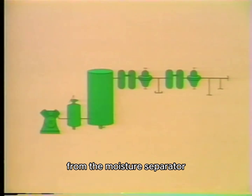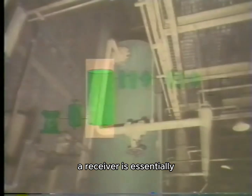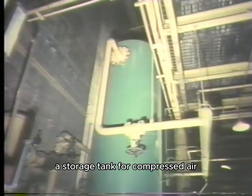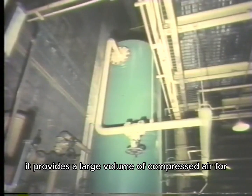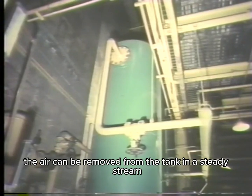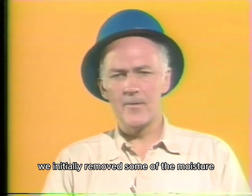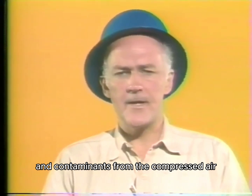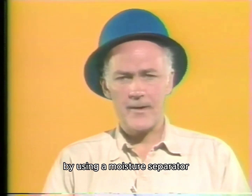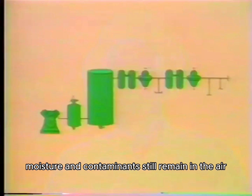From the moisture separator, the compressed air flows into a receiver. A receiver is essentially a storage tank for compressed air. It provides a large volume of compressed air for the many uses found in the plant. The air can be removed from the tank in a steady stream and can meet any momentary change in demands on the system. We initially removed some of the moisture and contaminants from the compressed air by using a moisture separator. However, moisture and contaminants still remain in the air.